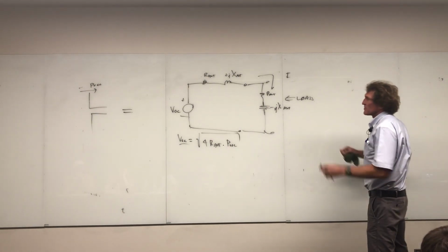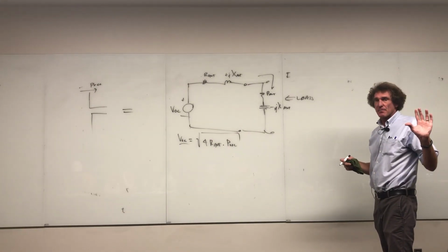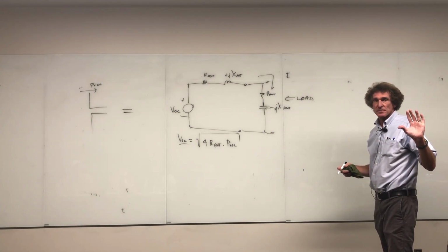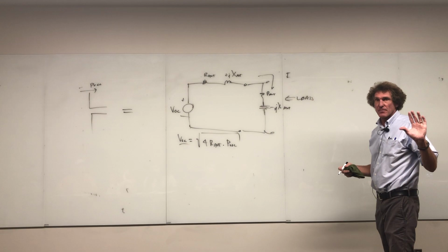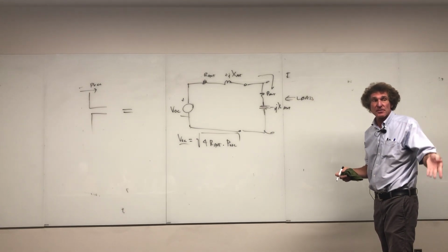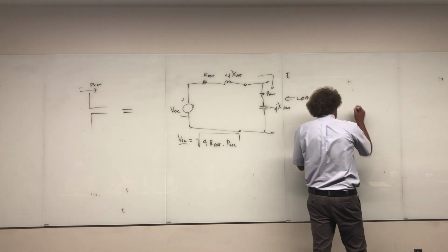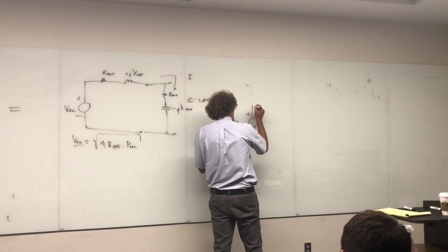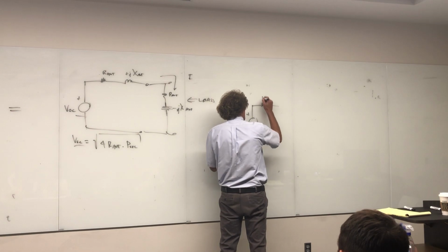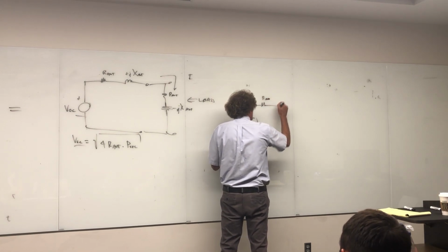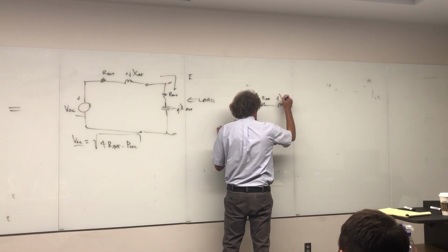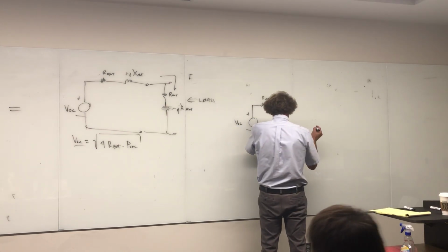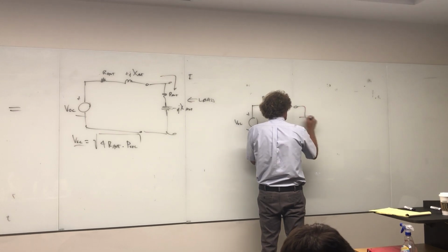Next, we say that suppose I have a half-wave dipole and it's receiving 2 watts. But attached to that half-wave dipole, in ideal, I attach a different load. Then I do this, really. I have my V open circuit that I know how to find. I have the antenna impedance, so I have R antenna, and then plus jX antenna, right? That's the antenna impedance. Here's where I attach my load. Now I put my load in there,